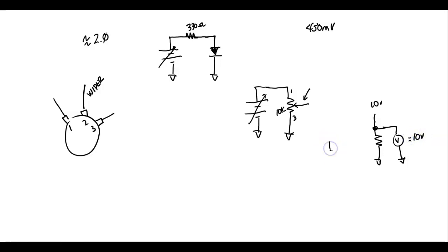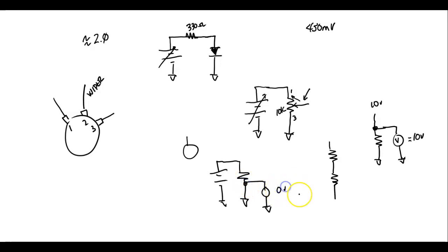Now, if we come over here and do this, this is when we're going to adjust the pot. So this is what the pot turns in. So what I just showed y'all, first of all, is if we had the wiper all the way up at the top. If I put the wiper all the way down at the bottom, we end up with this circuit right here. If this is 10 volts, we end up with this circuit. So what would my voltmeter measure there? Our voltmeter is going to measure something, but it's going to measure 0 volts, right?